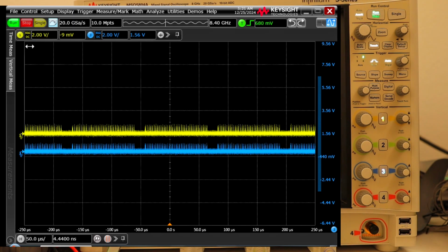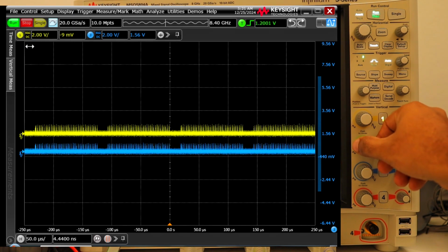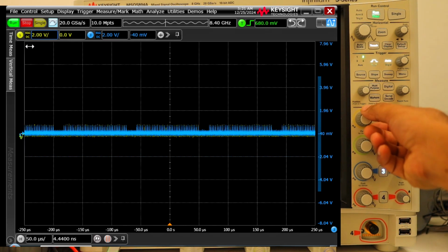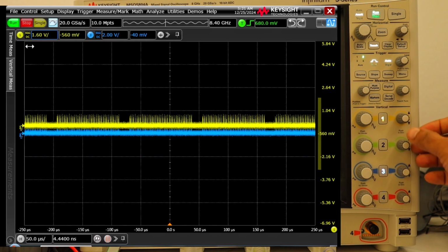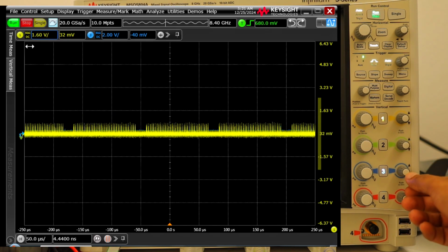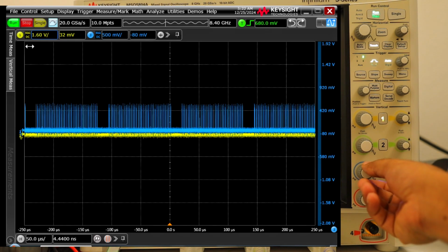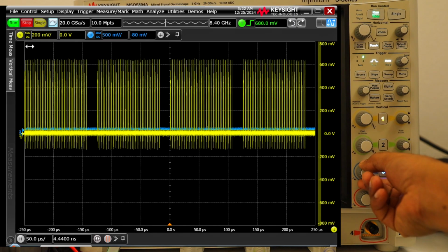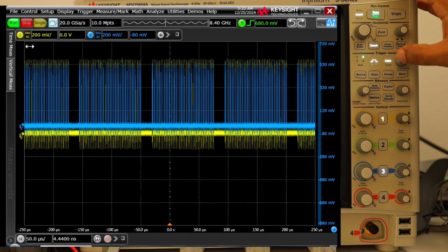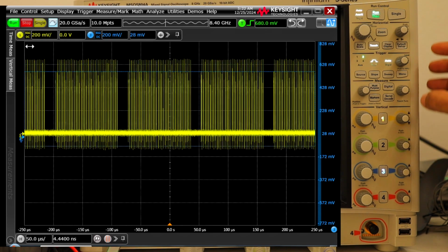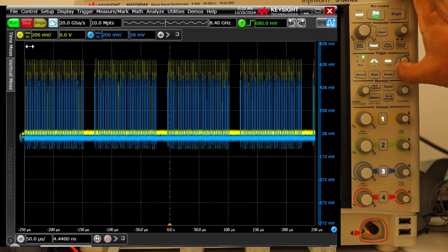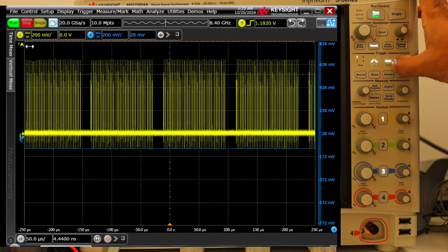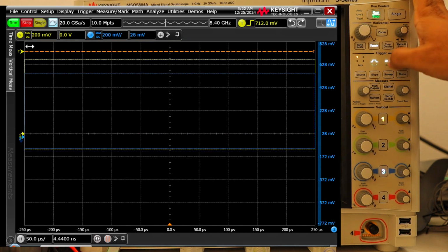So you now see the signal level is very low. It was expected. So we'll increase the time base. So increase the voltage base. Set the trigger point a little bit lower. Trigger is right now set to channel number 3. Let's set it to 1. Now the edge trigger should be a little bit lower.